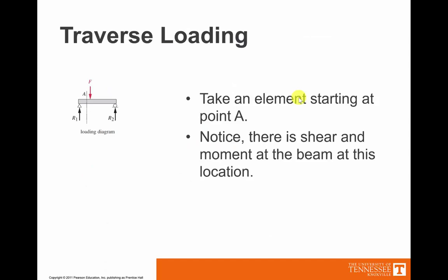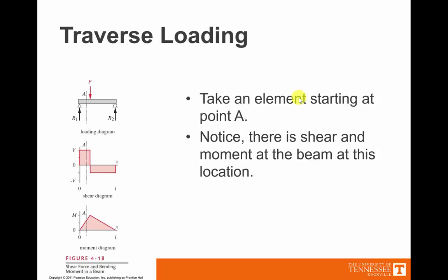Okay, so the last section of things we're going to talk about is now to say, well, what happens if there is shear and moment happening at the same time? So consider this loading diagram. Now there will be both shear and moment at the same location. And let's take a look. There's our shear diagram. So at this particular location A, there is a shear force, and there is a moment force that's occurring at the same location.